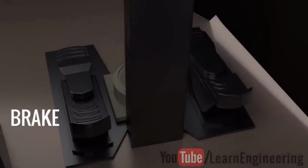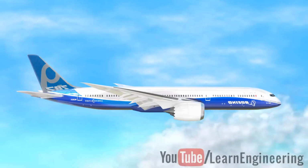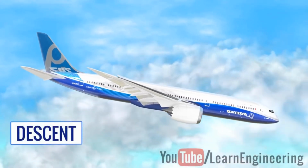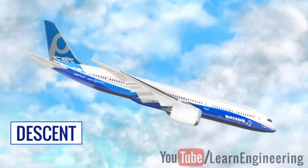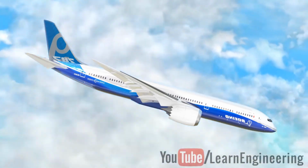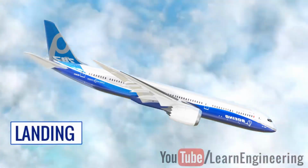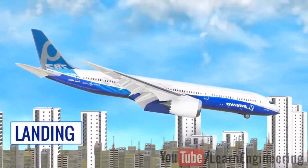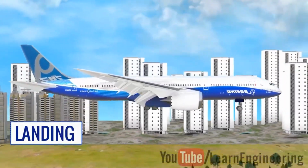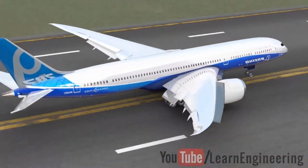To descend the airplane, what pilots do is decrease the engine's thrust and keep the nose of the airplane down. You can see this is exactly the opposite of the climb operation. As the airplane loses speed, it gets ready for landing. At this stage, the flaps and slats are activated again. These devices also increase the drag. To increase the drag further, a wing attachment called a spoiler is also activated.